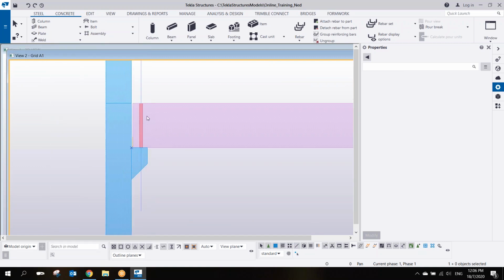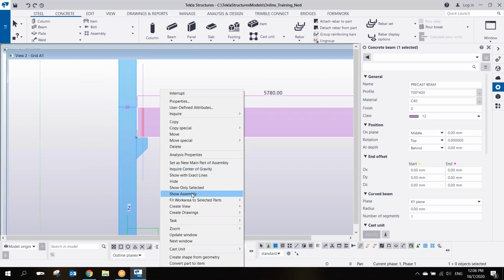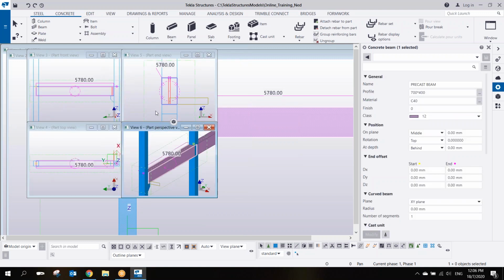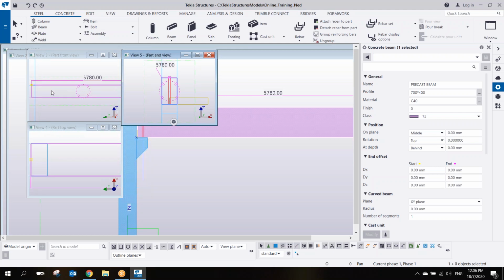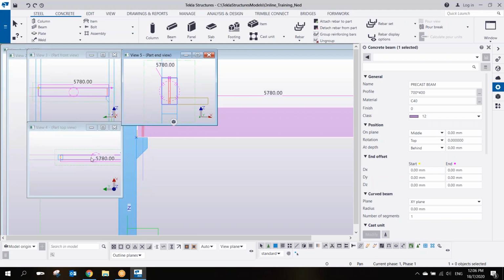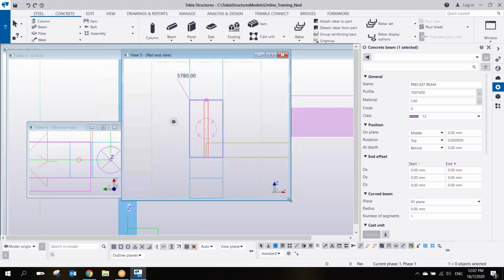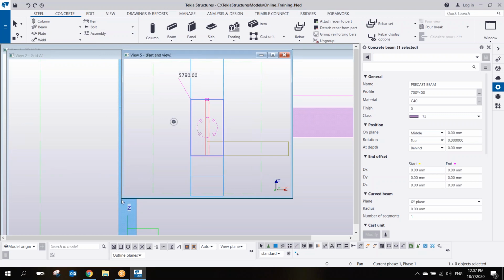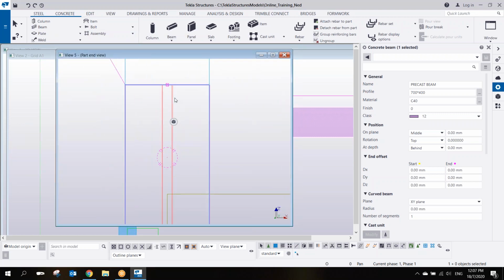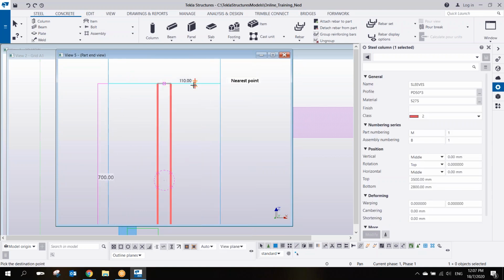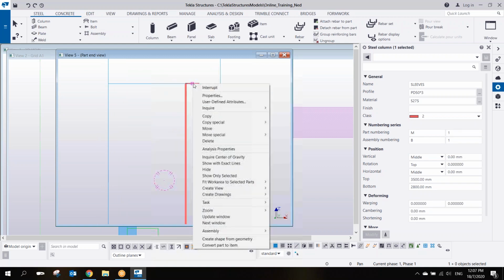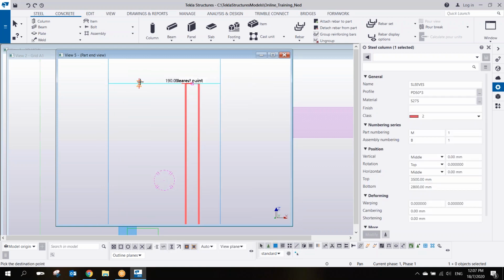This time, what I'm going to do is create basic views of part, and then I will go to the top view. Where's the top view? Yeah, top view. I can use the top view or this side view, or maybe this end view is better. So I will select this one and then move. Let's say I'm going to move 100 here, and then here copy 200.